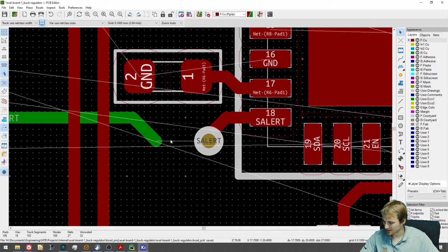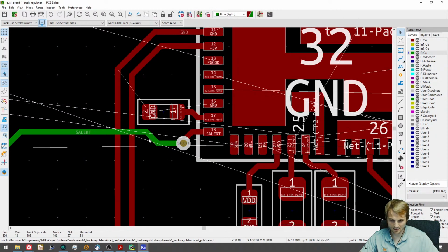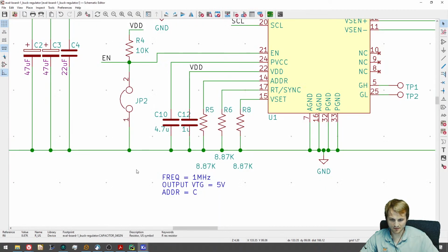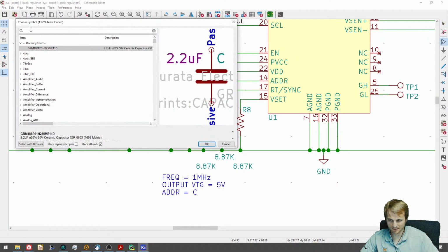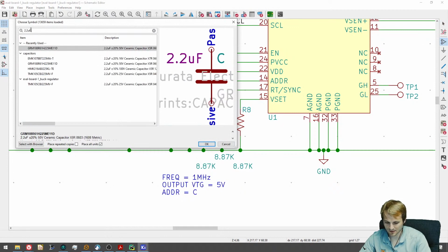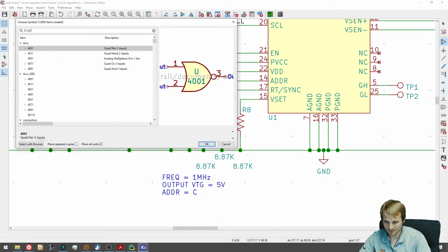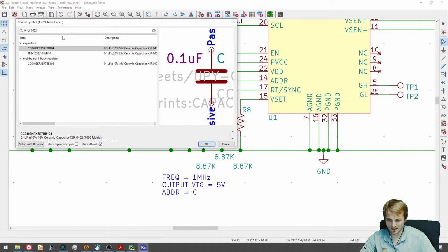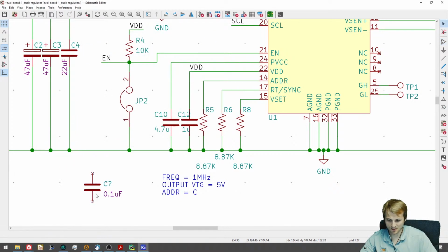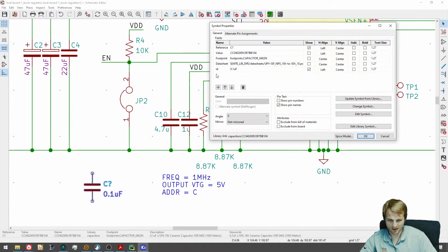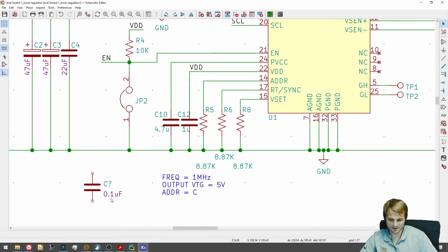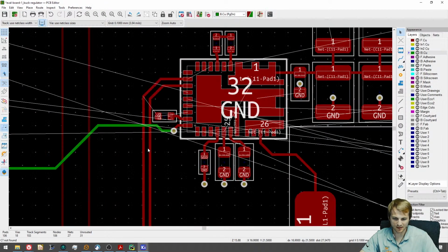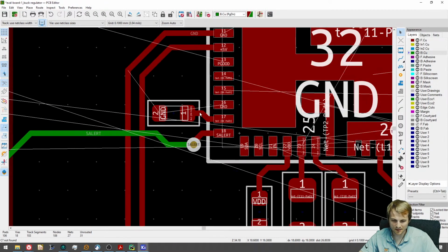Any BOM optimization regarding footprint and value? So this is not the way I do layouts at all. When I'm doing a layout for work, I have a library that we use. So like if I want a 2.2 mic that's 0603, I have one saved, or like a 0.1 mic 0402. I've got some here. So now these are fully linked to ID. It should have a manufacturer's field, data sheet, footprint, all that. So the BOM is essentially generated on the fly. But for this, since I'm not going to be sharing our library, I'm just doing it like, I guess, the standard KiCad way.